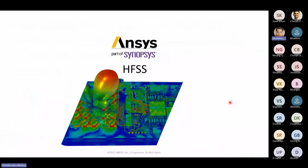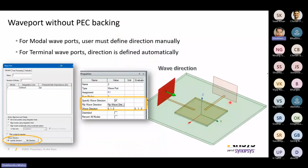That was for the HFSS 3D layout. Now I move to HFSS. In HFSS, a PEC backing part is enabled. When designing a port, such as a lumped port or wave port, the PEC backing which was defined was not enabled in the previous versions. Now in 2025 R2, you can directly enable the PEC backing to override the issues you face while enabling the port.